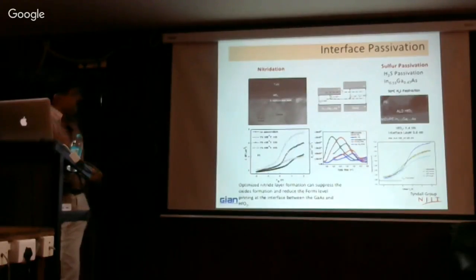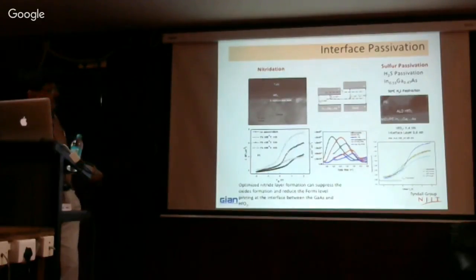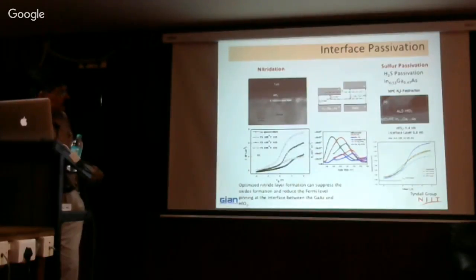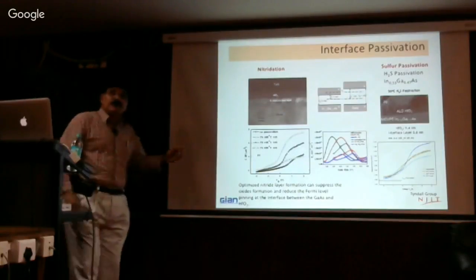Then they also found, look at the CV curve, it doesn't look like a CV curve, and all the values are different. See, if you change the frequency, this is actually as a function of frequency. Your question was like that, wasn't it? First of all, this is not flat, this is the accumulation capacitance. And also, it doesn't look like a standard MOS CV curve. And this work is publishable, by the way.